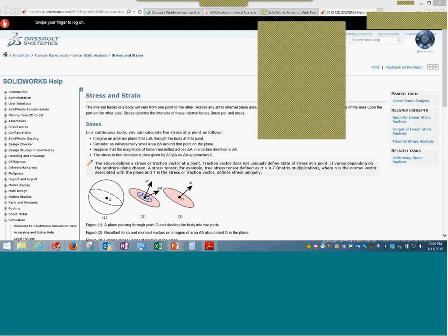Of course, these displacement values are available at different locations inside the geometry as well. But if I take that particular element, it is nothing but the change in length of that element compared to the original length, which is giving the strain. And the strains coming up in each element, seen in 3D, these summations of strains are leading to the total displacement of the entire geometry.